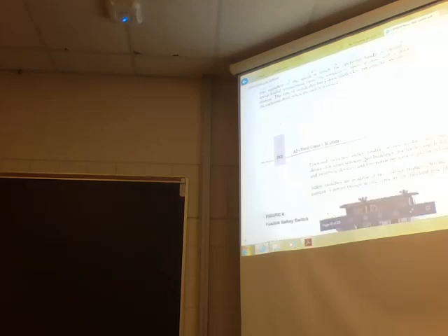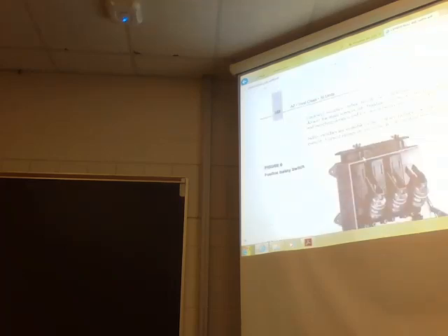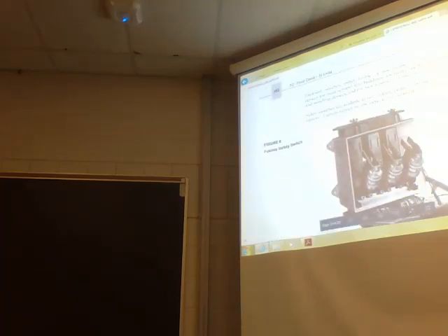Enclosed switches, either fusible or non-fusible, are used as disconnecting devices for many services in buildings, for feeder and branch circuit protective and switching devices, and for motor protection and switching. Safety switches are available in 2 voltage ratings, 230 volts and 575 volts AC. Current ratings are the same as for standard fuse clip sizes.